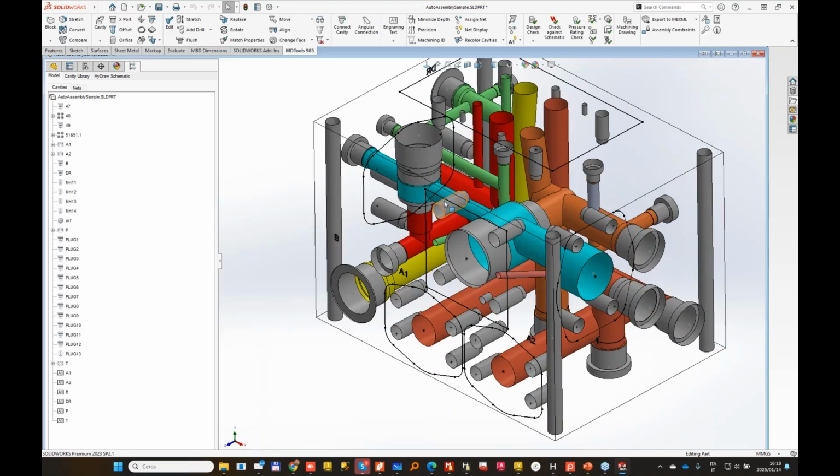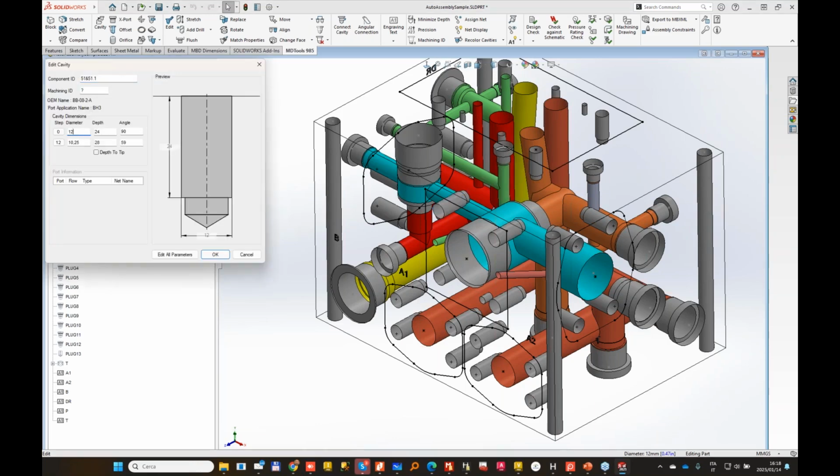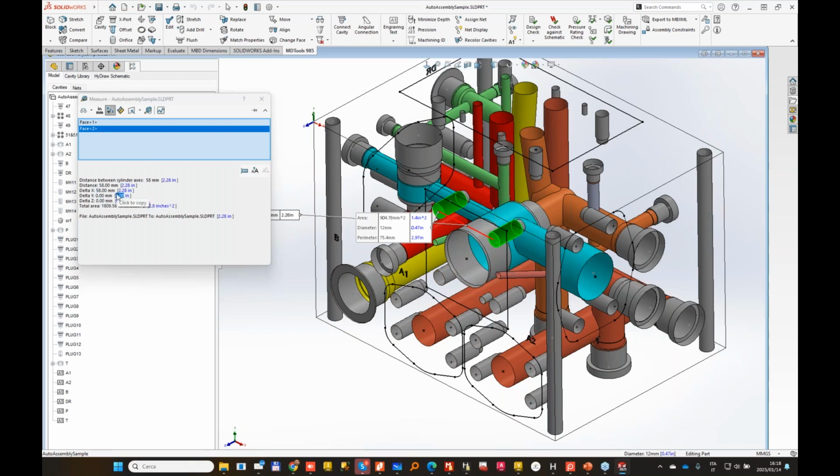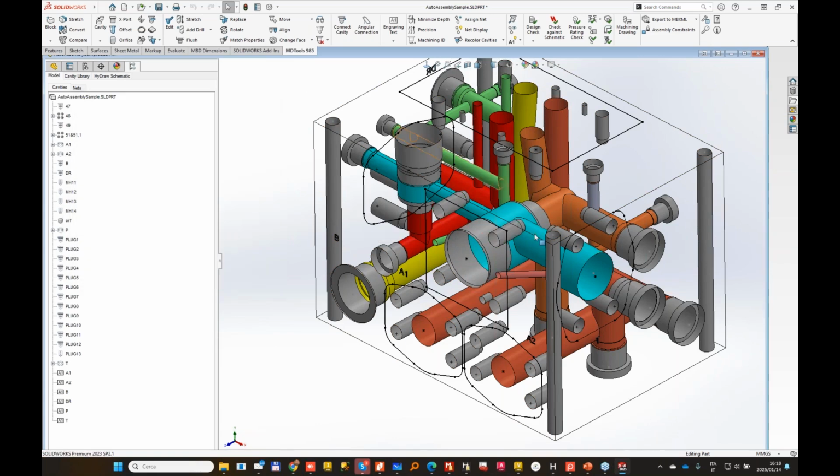So here we have the footprint, and I want to create the bolt kit for this footprint. So we have M12, and the distance between the bolts I could see in the library manager as well, but it's 58 millimeter. So first I want to prepare the M12.